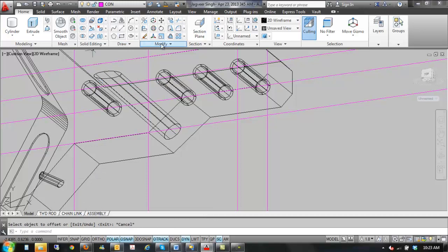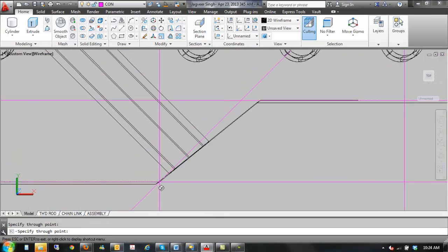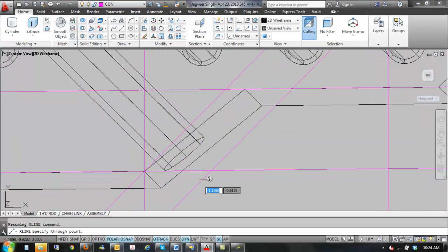And now you put one on an angle. And draw. Right at that intersection, so that's what you've got to saw off. So now you got enough geometry on there, you can make a little polyline.